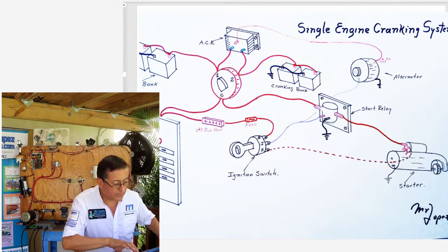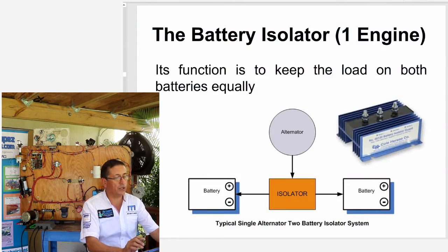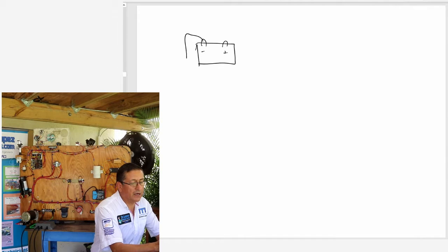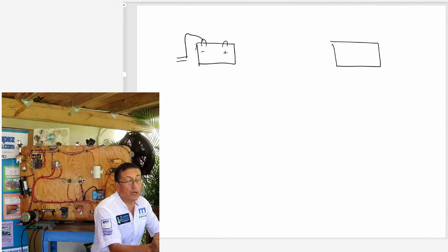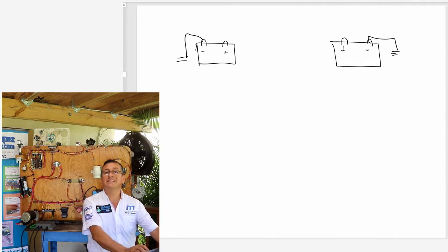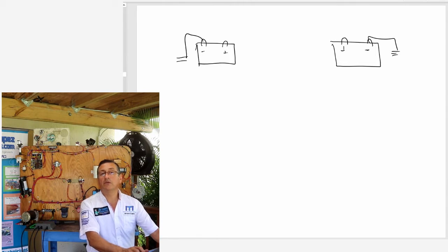All right, this is the diagram that we are going to connect. I have 2 battery banks. I have 1 battery bank here, that's the positive, the negative. Remember, all the battery banks, the negatives should be connected together and connected with the negative bus bar, and the negative bus bar connected to the bonding, and the bonding connected to the sink. We are going to learn about that in chapter number 10 dedicated to the bonding system.